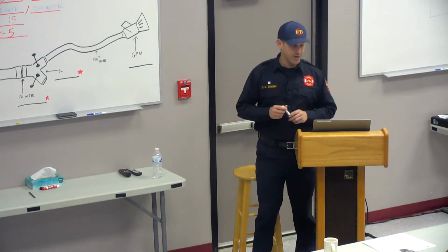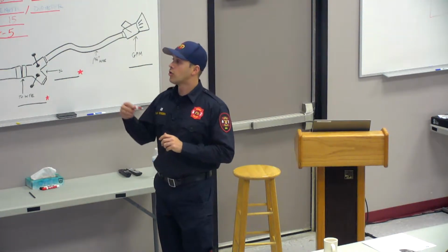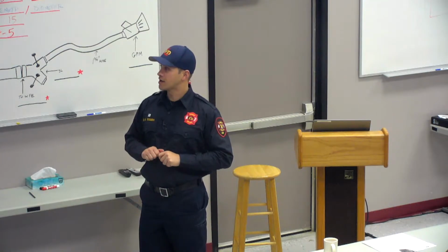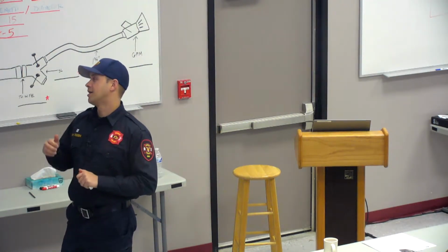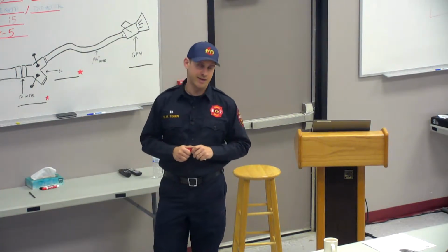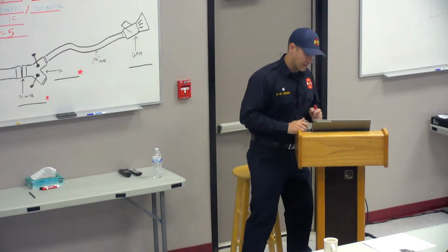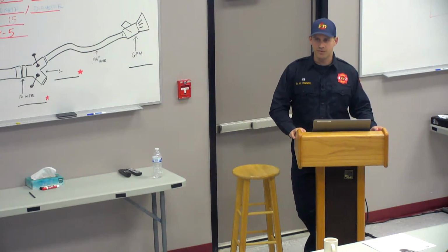This equation here is out of the book. This is one of the equations that they go over again and again. It's just the equation for friction loss. So you have a friction loss coefficient, a flow rate, which we always assume is gallons per minute, and hose length. I would absolutely understand the equations in this chapter for the sergeant's test.